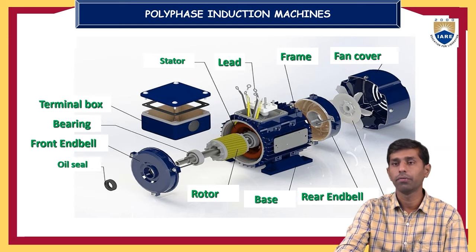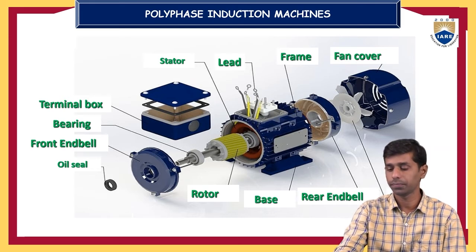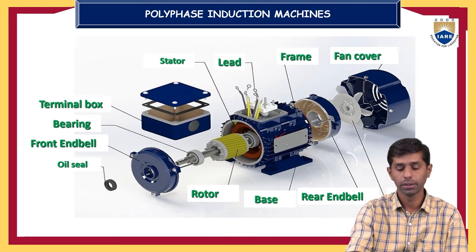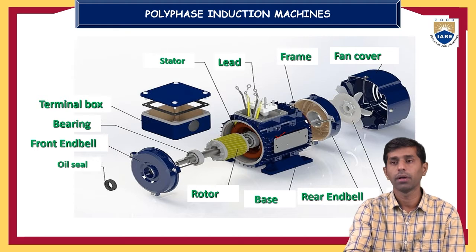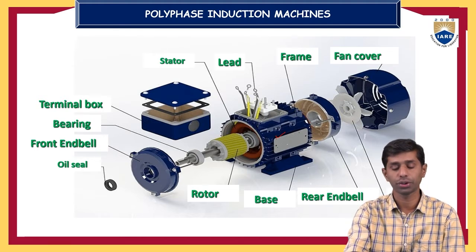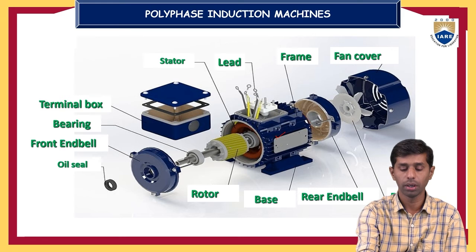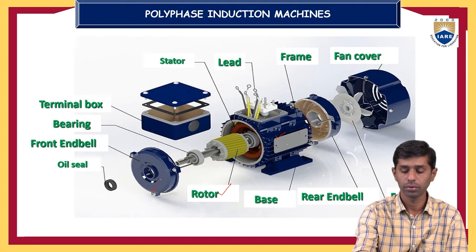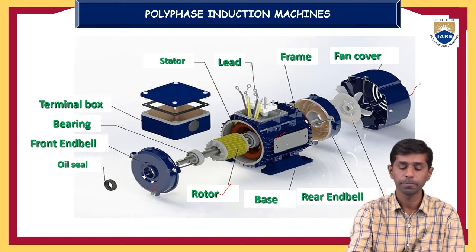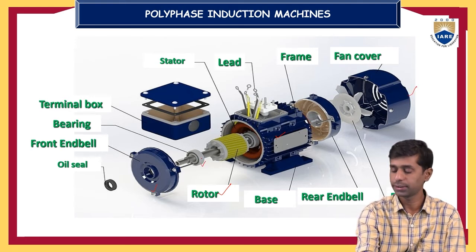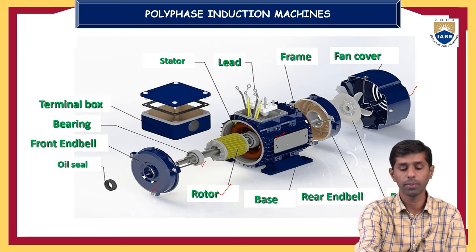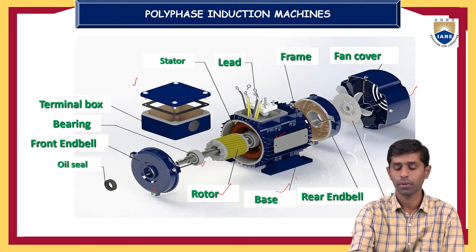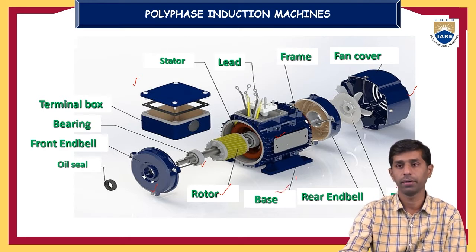See here the complete view of a three-phase induction motor. Here this is the frame, which we can also call the yoke of the three-phase induction motor, and this is the rotor, two end covers, front end side and back end side, bearings, terminal box, base, and cooling fan.